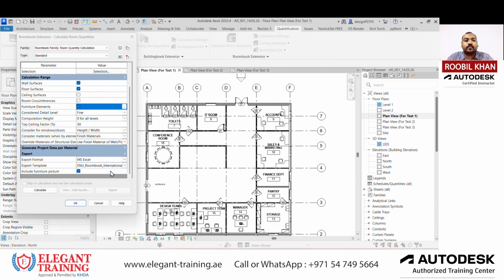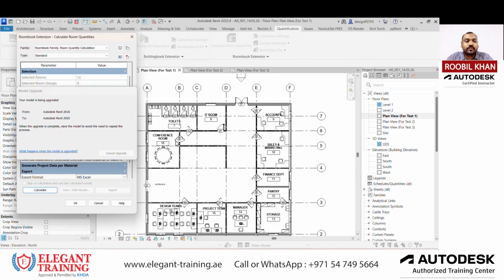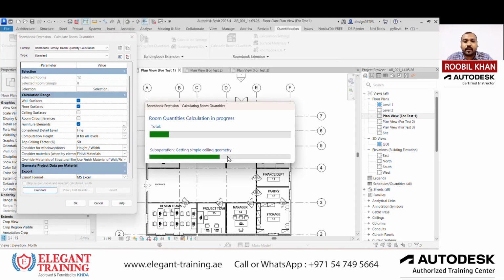You can export your quantity to the Excel file format, or you can also change this to the Design Web format or even CSV. I prefer the Excel quantity which I need. So from here I'm going to click Calculate. Once you click Calculate, this window will appear. It shows how many rooms you have in total, so it's taking the entire quantity.